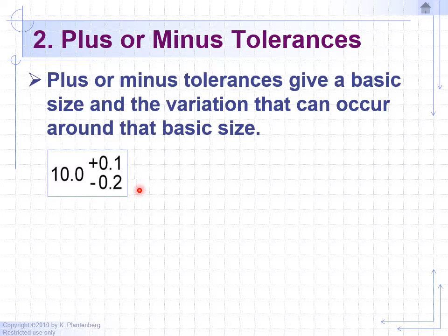And the machine shop is going to ask you for a tolerance. How much can they be off by? So you're going to tell them, okay, you can be on the heavy side, or I should say the longer side, of plus 0.1. So if you add plus 0.1 to the 10, that means the maximum length you'll accept is 10.1. And they're going to ask for a minimum. What's the minimum length that you will accept?